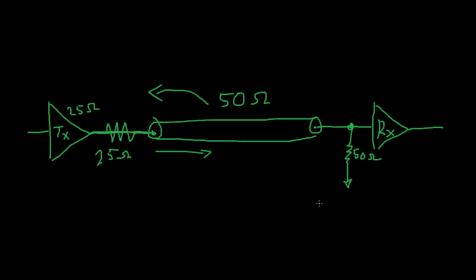Now what's going to happen whenever we transmit this? Now we've still got the same basic concept going on over here. You can draw your ideal buffer with 50 ohm resistor. And then we have our transmission line that also acts like a 50 ohm resistor. Whenever we have our 50 ohms here and 50 ohms there, exactly half of our signal is going to show up right here. So we will go ahead and look at VCC up here. We have our signal coming in and jumping up to half and then staying at half.